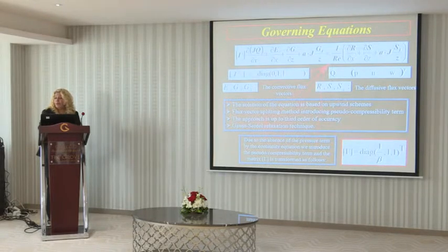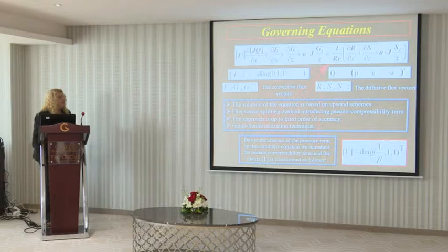In this paper, I will present some examples for laminar flows and viscous flows, but definitely we can solve turbulent flows as well with very high accuracy, with the k-epsilon model as we have done. The specific numerical technique uses the artificial compressibility term, as you can see, in order to manage the absence of the pressure term that we have in the equations.